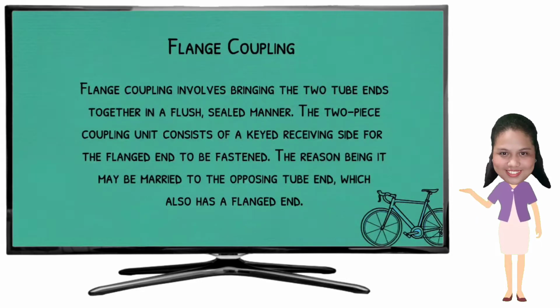Flange coupling is similar to sleeve coupling because it is simple to construct. Flanges are present on both sides of the two sleeves. In this case, both flanges are made up of an equal number of threaded holes for fastening. Bolts and nuts are then used to connect the flanges. On the hub and shafts, a key area is also supplied to prevent slippage.